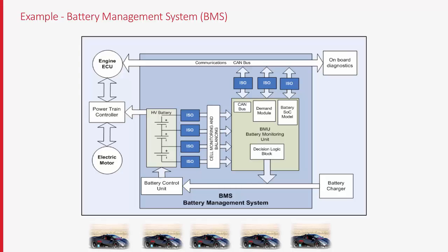Here's an application that demonstrates an isolator's attributes of both safety and level shifting. Battery management is critical for lithium-ion batteries used in electric and hybrid electric vehicles. This system maintains the battery's charge status, protects the cells from damage due to overcharging, and prolongs the life of the battery. It also communicates the status information to the engine's primary electronic control unit. Battery arrays can be hundreds of volts and considered potentially lethal. In addition, common mode grounds must ultimately be level shifted to the ground of the system. One isolation device can perform both tasks seamlessly.